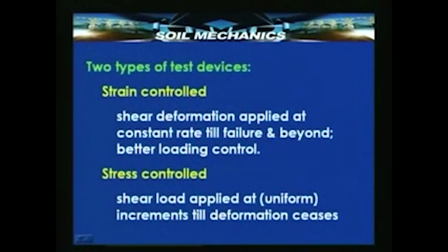So, we can either control the strain at which the movement takes place, or we can control the stress that is applied. Accordingly, we will have a strain controlled device where shear deformation is applied at a constant strain rate till failure, and even beyond if we are looking for testing beyond the failure state as well.